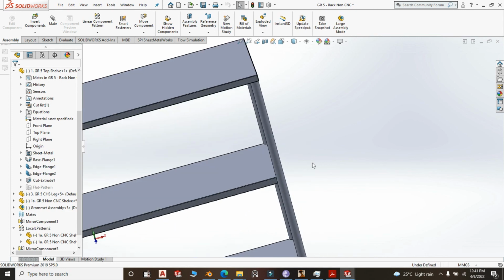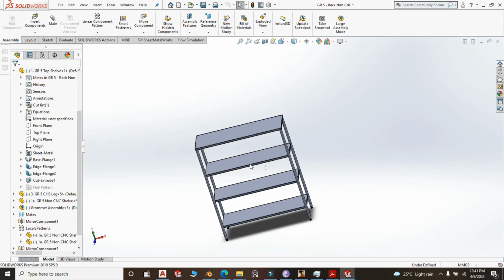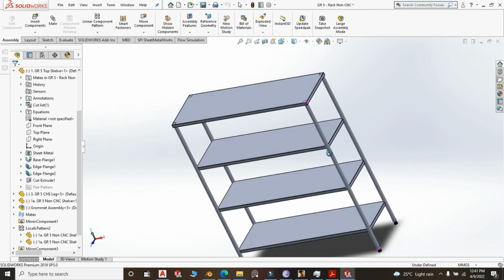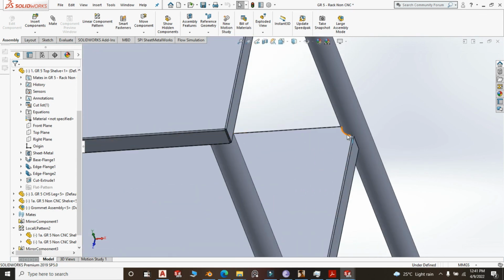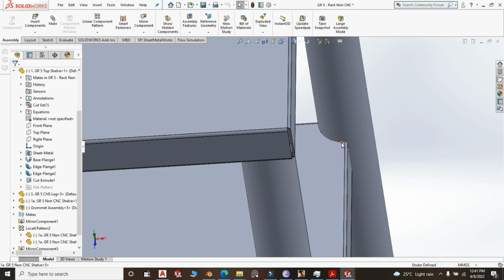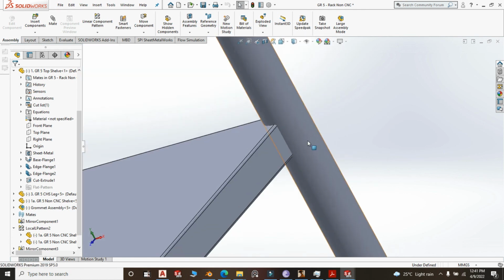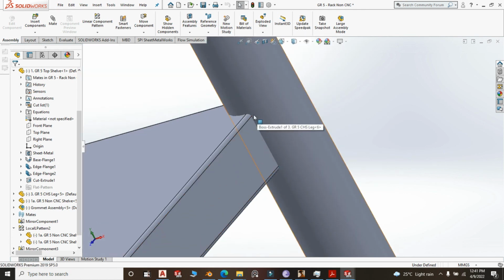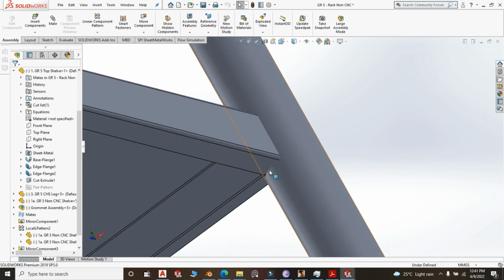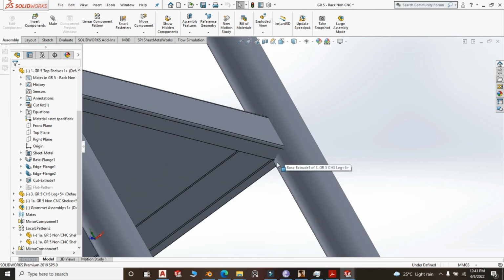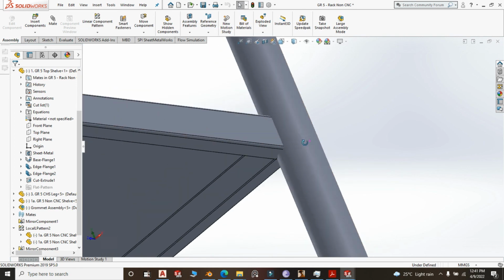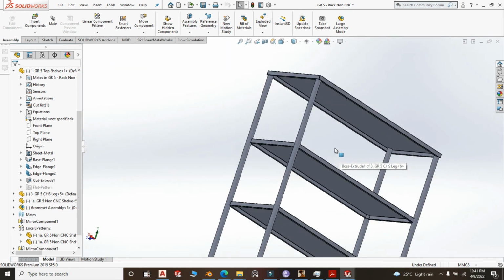Now also, the reason why I said this rack is far more beautiful and comes out cleaner than the other one, whether you have CNC or not, you are not going to weld here because it is absolutely hard to do the cleaning, and also the notch has to be perfect so that there is no gap. You don't want that to be hiding here. So where you're going to do the welding, right here between the shelf and the leg, that's where your welding will be, and a small weld under there. Here under, pickling paste, no polishing here, and on this other side polishing, right?